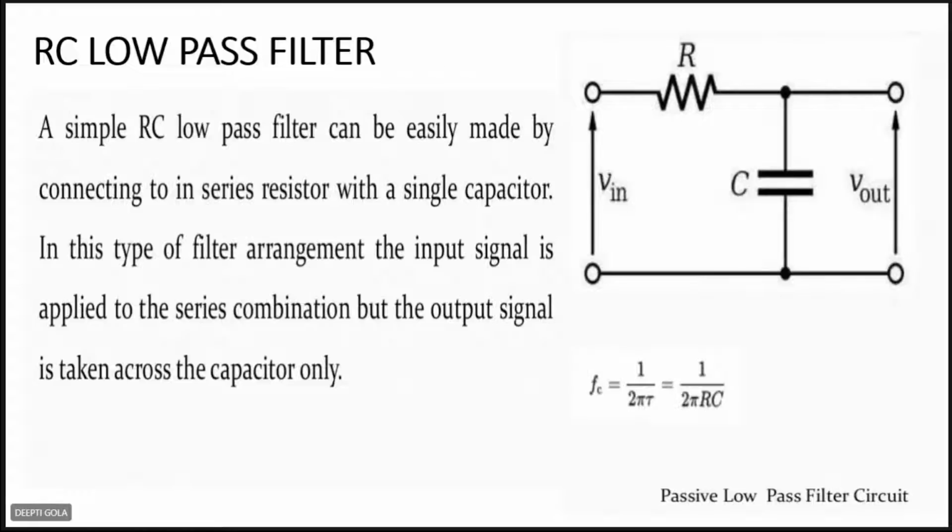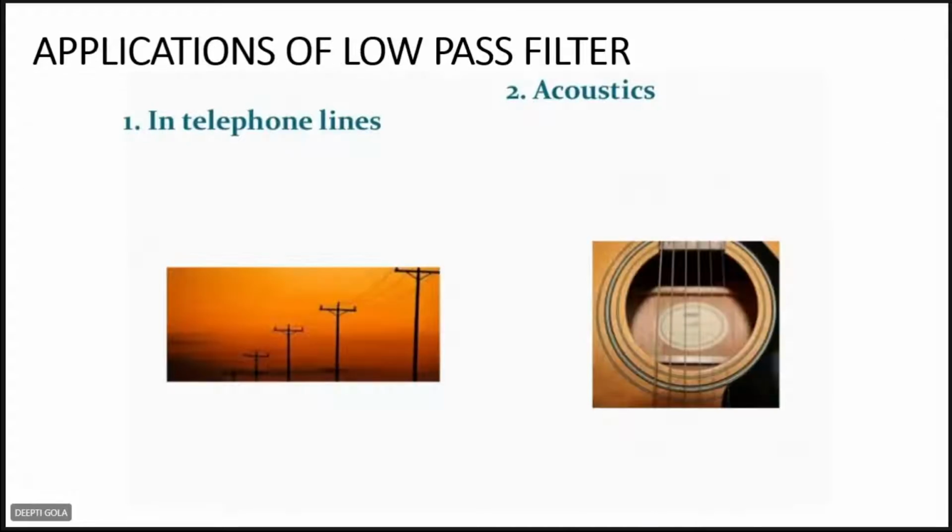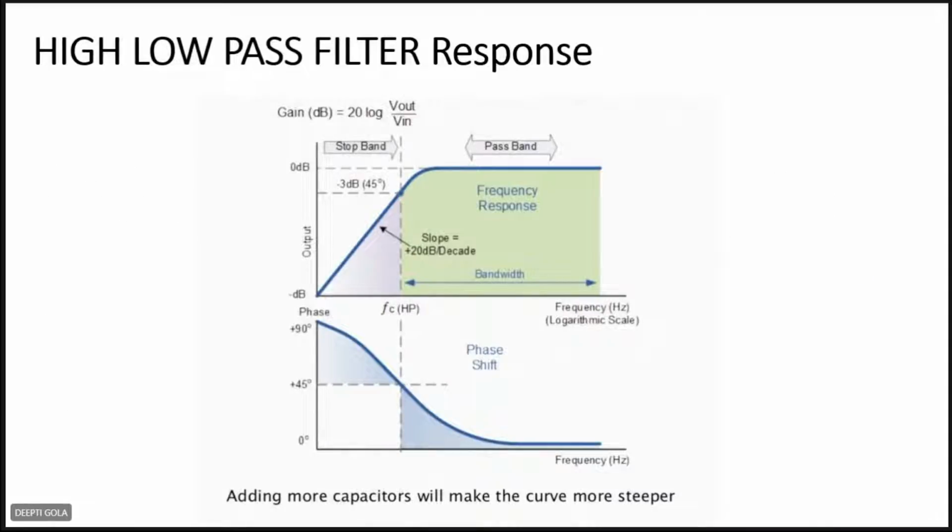Okay, and for higher frequencies, it will act as a short circuit. So this output line which you are seeing will be shorted, so there will be no drop at this output terminal. So the output will drop to zero for higher frequencies. Okay, so this is all about this experiment.